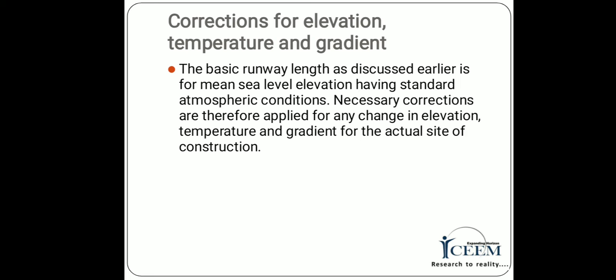Next point is corrections for elevation, temperature and gradient. The basic runway length as discussed is for mean sea level elevation having standard atmospheric conditions. Necessary corrections are therefore applied for any change in elevation, temperature and gradient for the actual site construction.